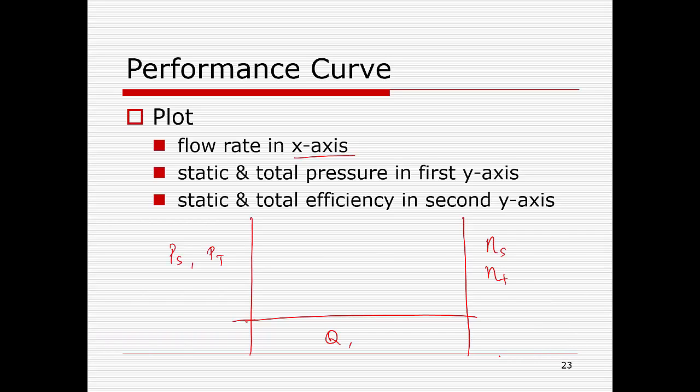The fan curve is nothing but the pressure head, or pressure provided by the fan, at different flow rates. The higher the flow rate, the lower the pressure. The lower the flow rate, the higher the pressure. And in order to do that, we have to have a long tube and a flow straightener to avoid any disturbances in the flow so that you can measure the velocity more accurately. And in order to measure it accurately, you have to measure it at 24 points after a certain distance along the length of the tube. And then you are throttling the valve to change the flow rate.